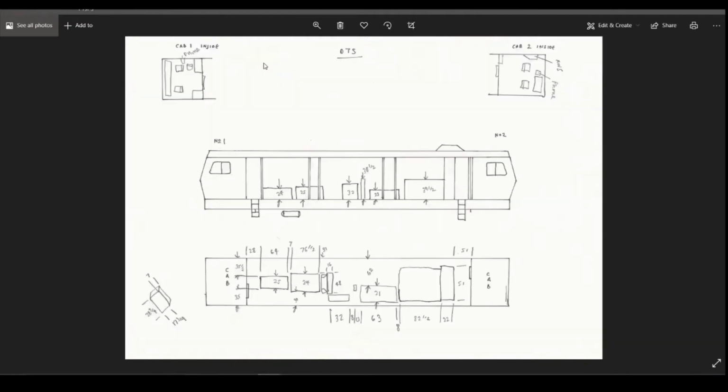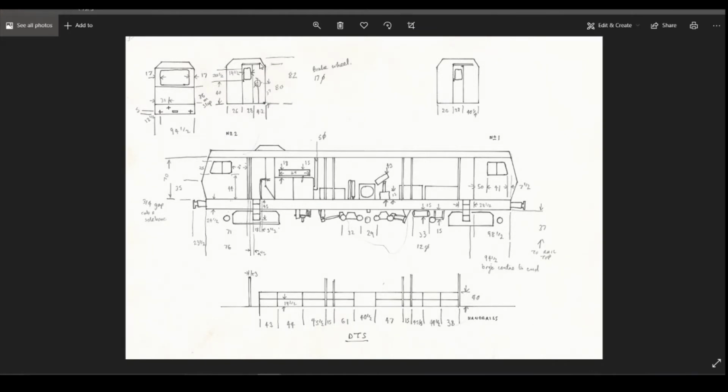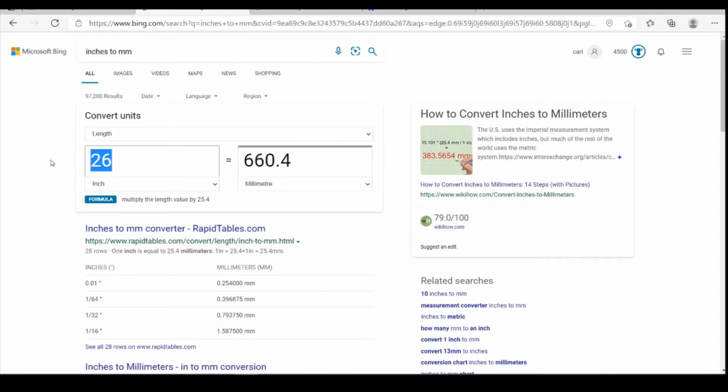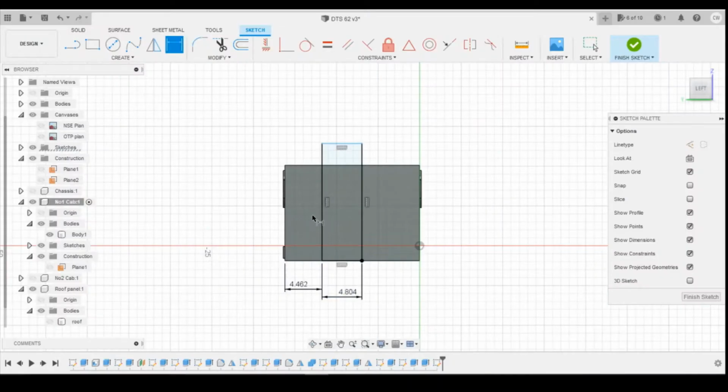And the next one is the height, which we're looking at is 80 inches. So it's 82 inches to the top of the range strip. So it's a 2-inch range strip, so we're going to go 80 inches to the top of the doorway. So 80 inches is 2032. I can define that height as 2032 divided by 148.